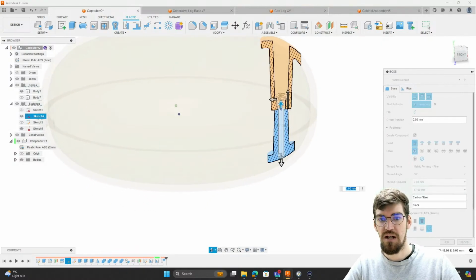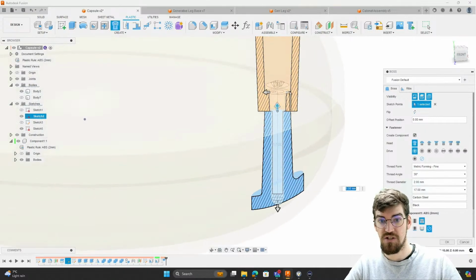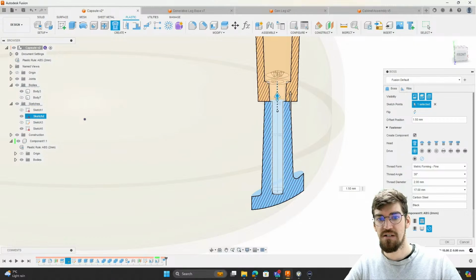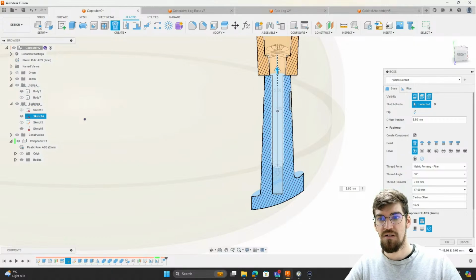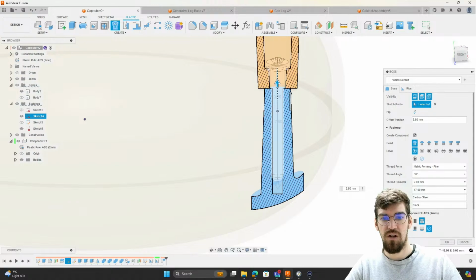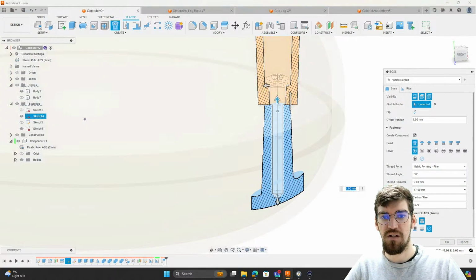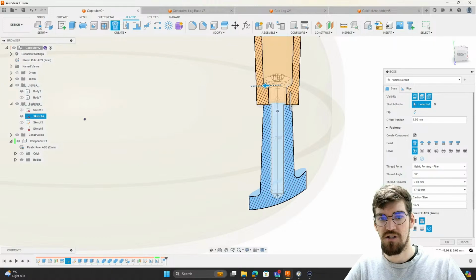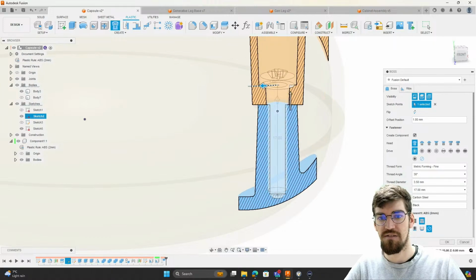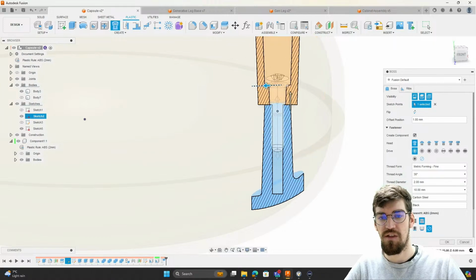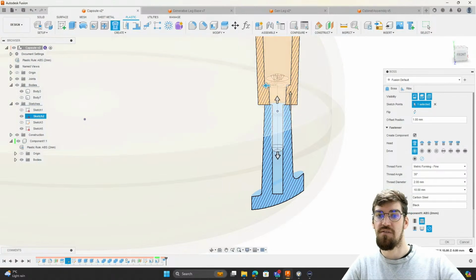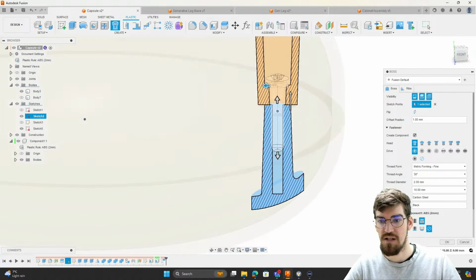Using the boss tool, I can then, based on the position of that point within the sketch itself, offset either in the Y positively or negatively, depending on my modeling direction. Or I've got the ability, as well, if I wanted to, to adjust the sizing of that boss, or rather the fastener, which will then drive the diameter of the boss as well.